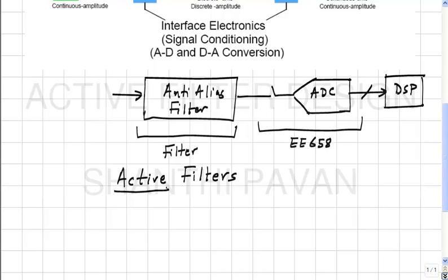Okay. So at these frequencies, making filters using passive elements can be done, right? All it takes to realize a filter is one inductor and one capacitor. To realize a second order filter, all that it requires is this. In fact, you can even do it with two capacitors and two resistors. You will not get as good a filter as you might want, but I am saying that it is very easy to realize